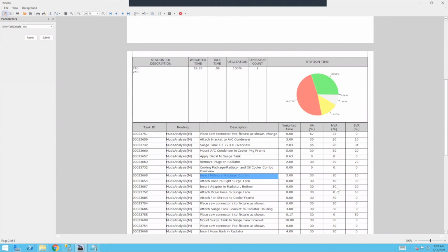To recap, you're doing time studies. While doing time studies, you're doing non-value added analysis of everything the operator is doing. You're then projecting that non-value added content across the stations on your line. You're seeing which stations have the highest non-value added content. You're targeting those stations. You're looking at the details of those stations in terms of which activities have the highest non-value added content. You can then go refine those activities, improve them, and reduce the non-value added content.